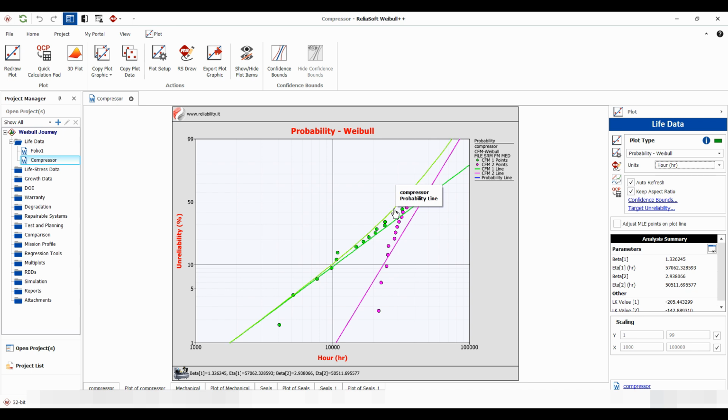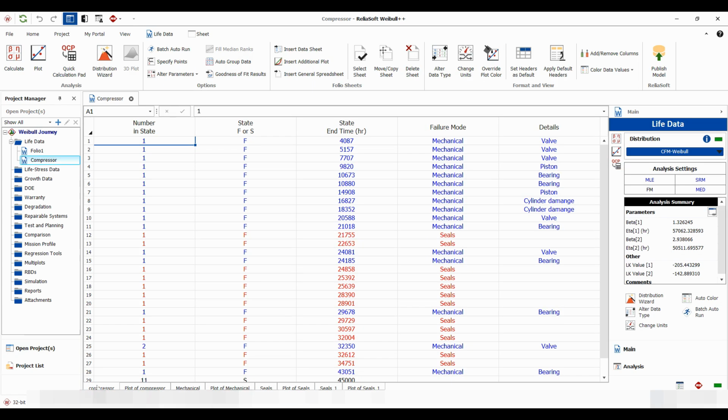The resulting model is the product of these 2 data sets. So it does not generate a final Weibull model, but it generates a resulting curve. And this is very useful in situations where, as we said, we've collected our data, but together with the numbers, we've also collected specific information on how the product failed. And based on that, we can decide perhaps to provide some solution to a particularly critical failure mode based on the graphical output.